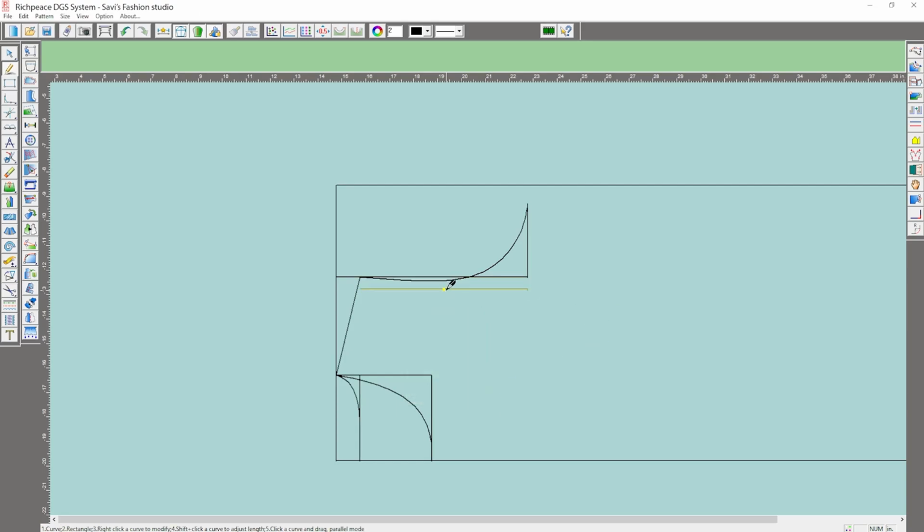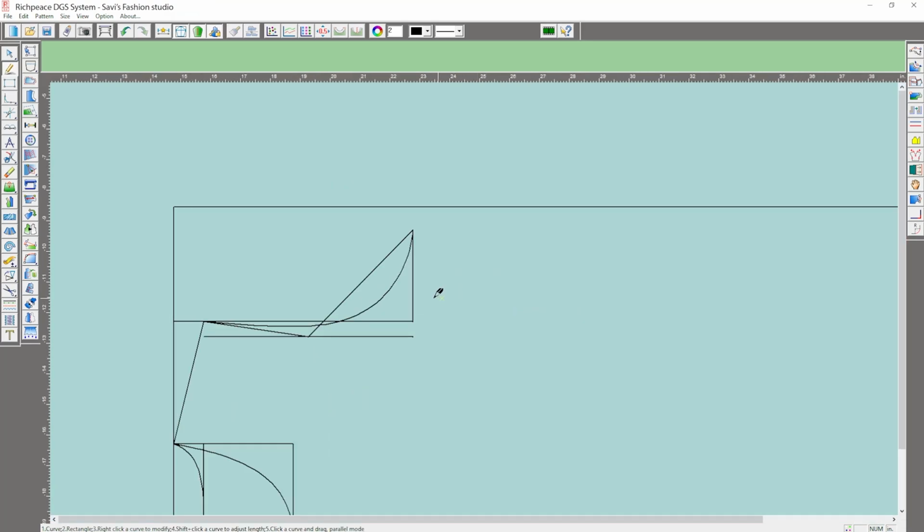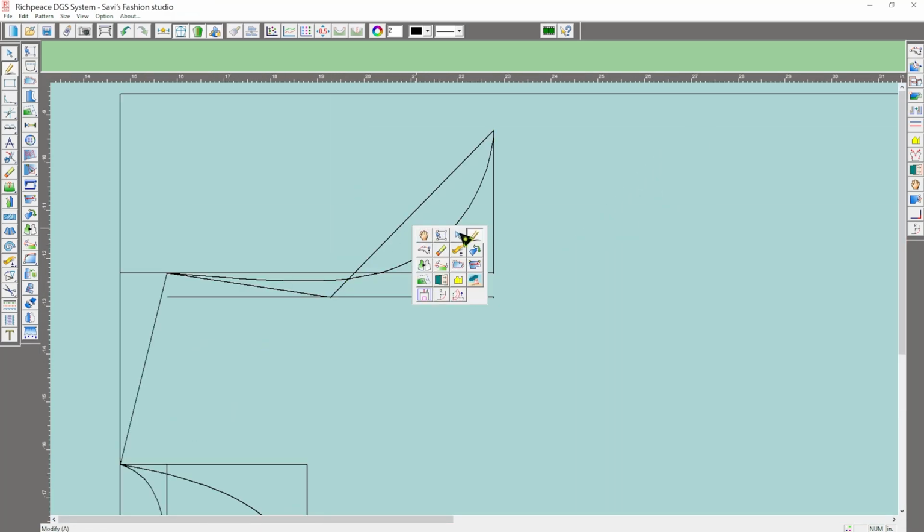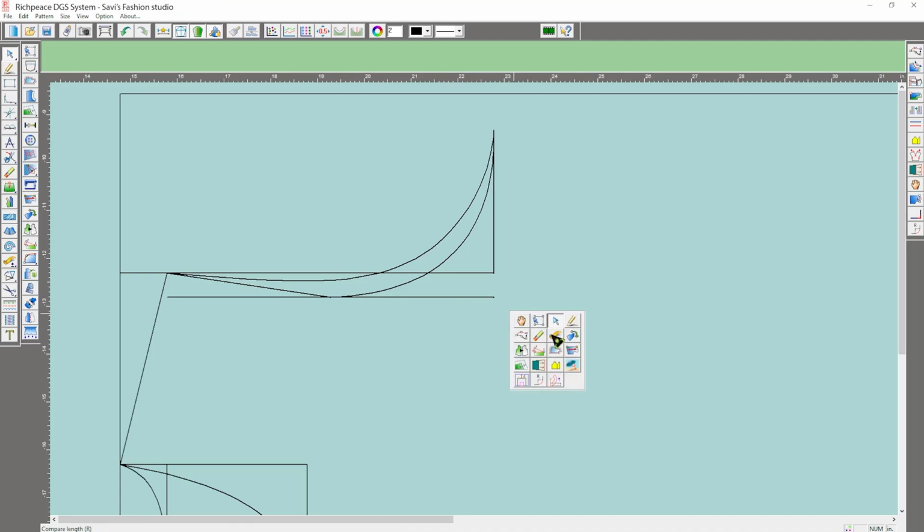Okay, and automatically a center point is always created when you do a line. Now I'll draw from here to the center point and right click again from here to here and right click. Let me zoom this. Now I'll take the modify tool and create a smooth curve. Now you can remove the unwanted line by clicking on the eraser. Remove.